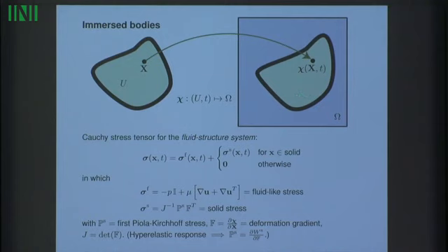And those solid stresses can come from whatever solid mechanics description you want to use. We are mostly using hyperelastic material responses where you have some energy functional that you can use to determine, in this case, the first Piola-Kirchhoff stress, but you can use anything that you like to tell you what the solid response is.